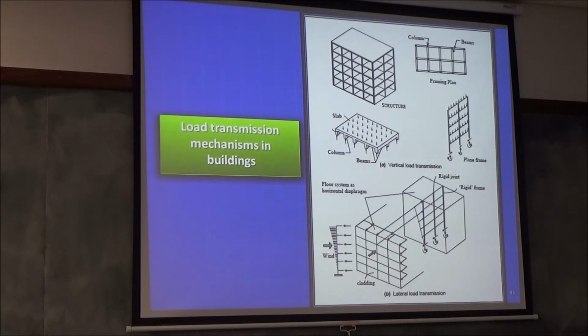It's strictly not true. You have to have some way of, you know what's the right thing you should say? You have a story shear. What is story shear? You assume points of contraflexure at mid height of all the columns. You take a knife and cut the frame at that level, starting from the top. You have some lateral shear. At every story, you have a sigma of column shear forces which must be equal to the load you're applying. Now you want to pass on that shear to the different columns in some proportion. Some people say it's in proportion to the bay width. Different theories are there. Some people say let's make it simple. Let's say the interior column takes 2 times the shear as the exterior column.